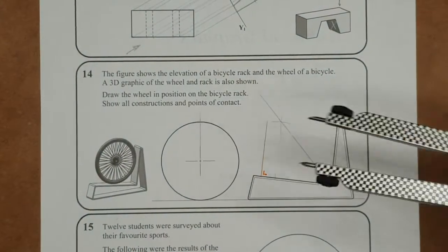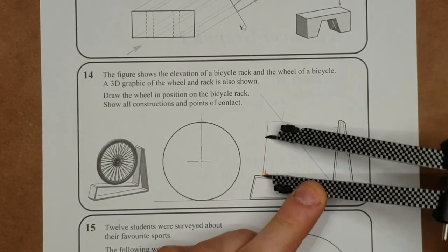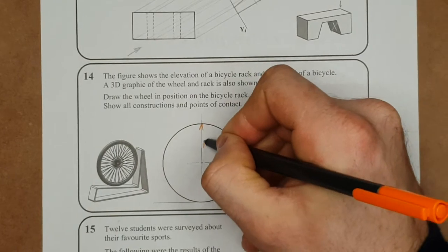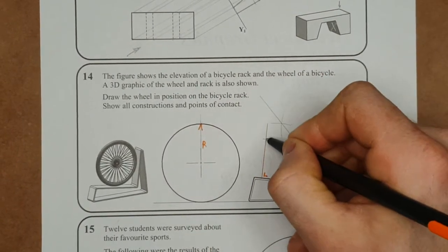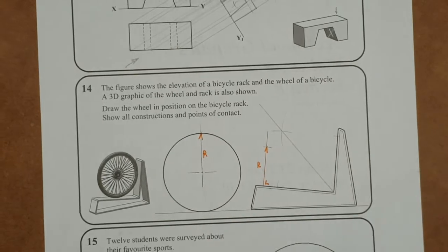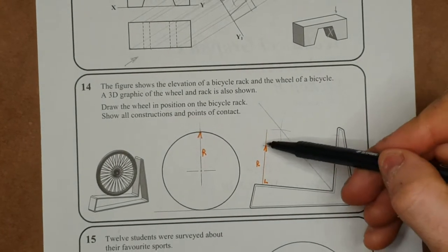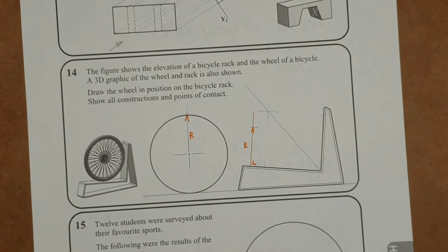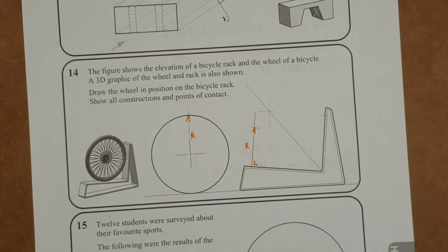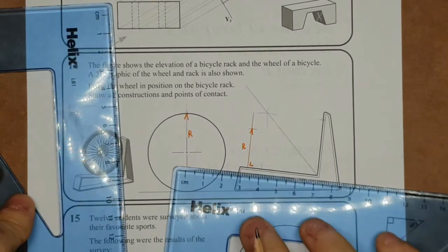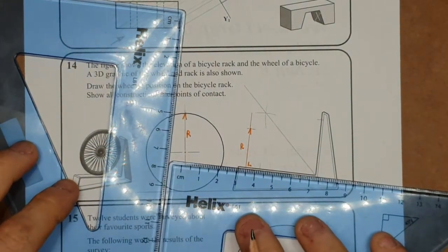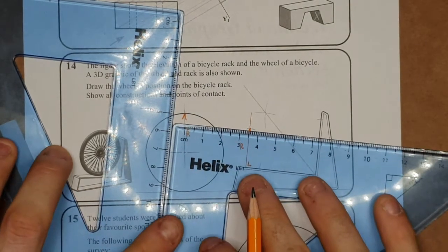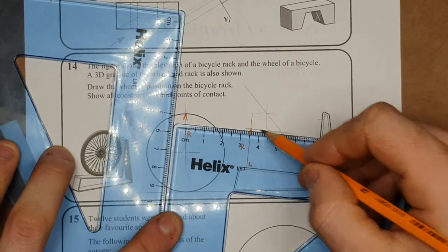I'll take the radius of this wheel and drop it. Once I have that radius added on there, there's my radius, added on here. Next thing I'm going to do is roll that wheel in towards the corner, and it's going to roll parallel to the ground. So as I said, I'm going to roll it in now by taking the ground angle or the base angle here, going up to my radius and rolling it in.